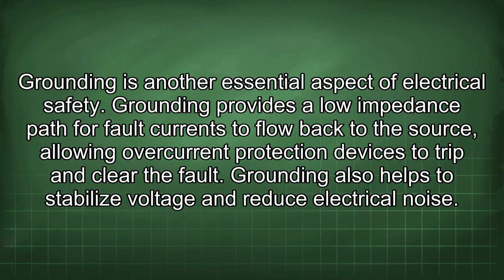Grounding is another essential aspect of electrical safety. Grounding provides a low impedance path for fault currents to flow back to the source, allowing overcurrent protection devices to trip and clear the fault.